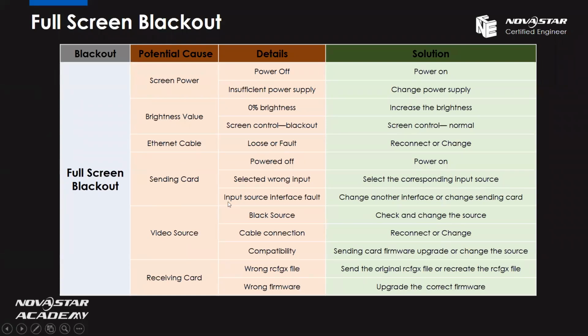Okay, and we also need to check the input source interface. If there is something wrong, we need to change to another interface. But sometimes maybe there are not enough interfaces. In this case, maybe we need to change the sending card.